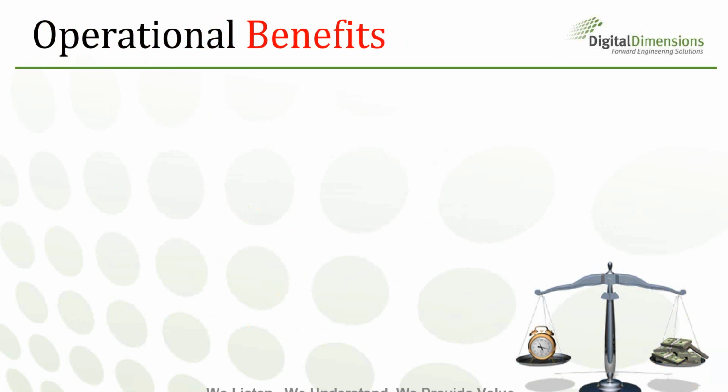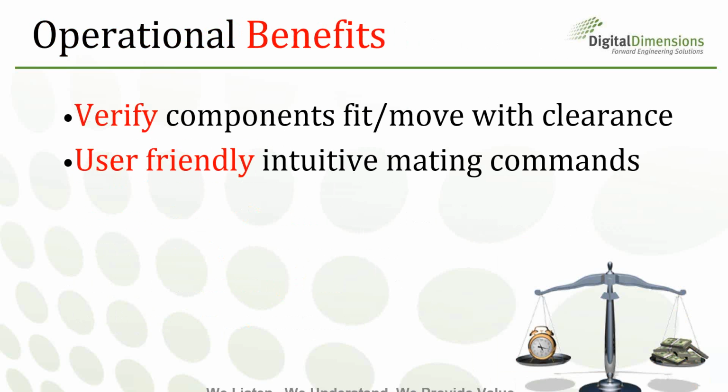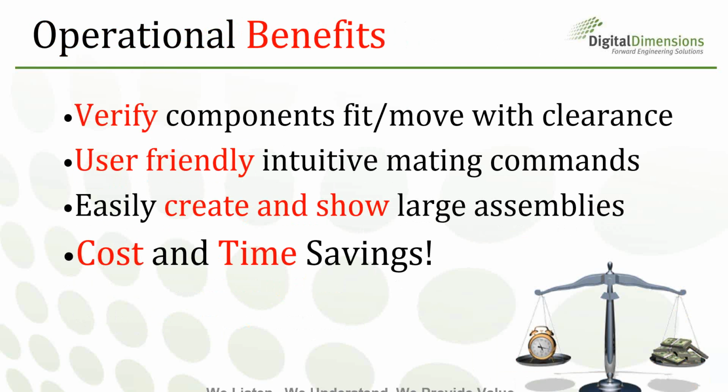So, some quick benefits of what we looked at today for assemblies. Assemblies are great to verify components fit or move with clearance. They have great, user-friendly, intuitive mating commands. Just remember that holding the control key and selecting the two surfaces, planes, or faces will bring up the mating flyout manager for you, so you don't have to go into the property manager. And you can easily create and show large assemblies. We looked at a bunch of options for doing that with the system options and other great tools to help speed up large assembly problems. And of course, the big one that we always harp on: all these things come down to cost and time savings.